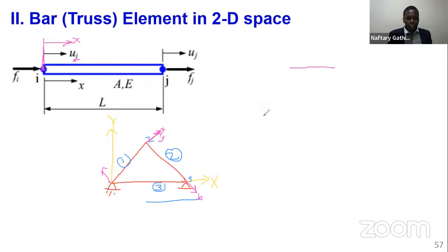What I was saying before I forget is that we talked of the load being applied at the nodes, but you may have cases where it's a bar element but the load is uniformly distributed, like there is friction. Remember, the load is only applied axially. So don't ask why I'm not applying it that way; I'm showing generally the way we show a UDL. It's because for a bar element, we are saying the load is applied axially. But now we are saying it's a UDL.